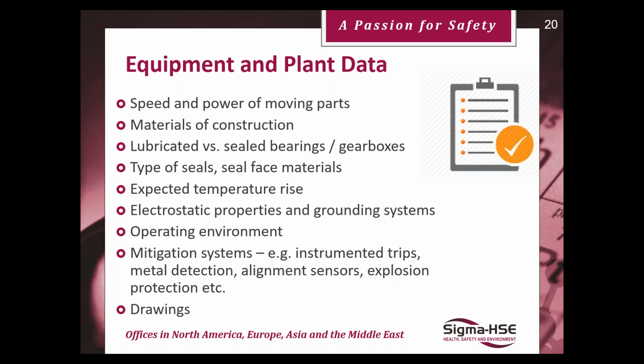So that could lead to issues with static electricity. So usually when you undertake a NIRA, a typical recommendation could be that you may need to earth all your equipment, or do a check for earthing, especially if something's been dismantled, when you put it back together. So that's one typical example.